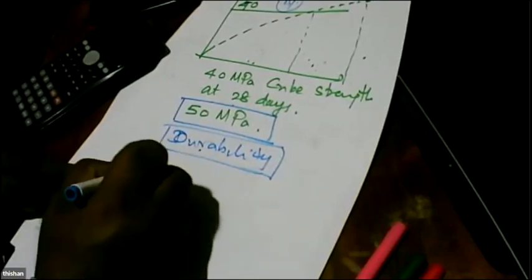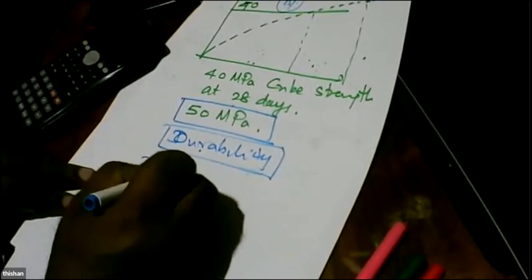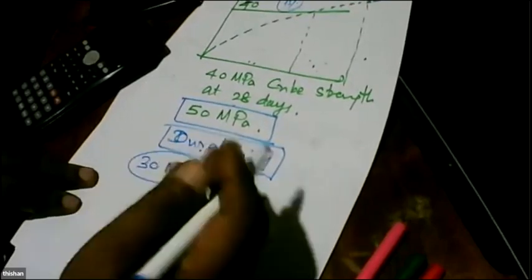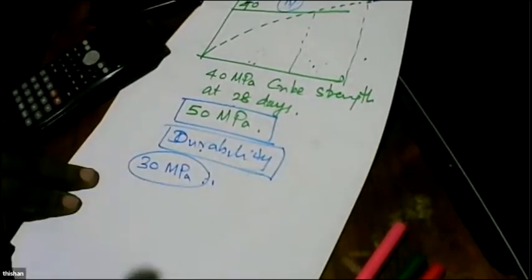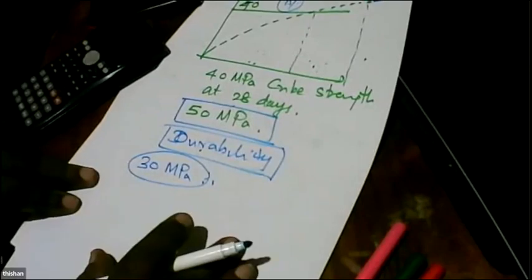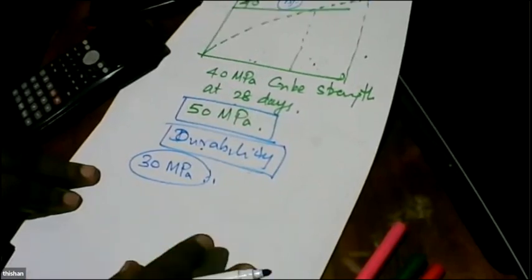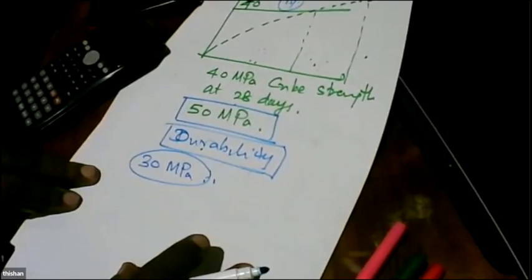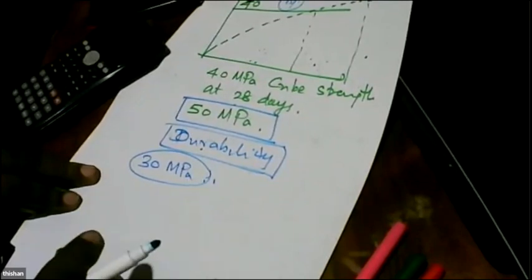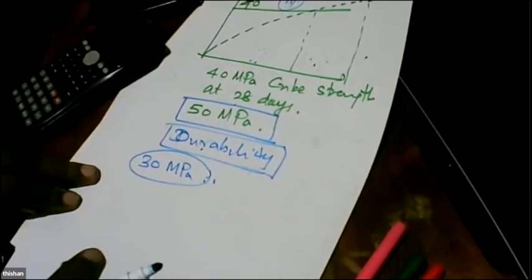If it is 30 megapascal or above, even 40 megapascal, 50 megapascal, you are going to end up with the same mass. So you can do the calculations and see. That is with my experience. I know if the bending moments are not very significant, like in our case, then the concrete strength is also not important as long as you have 30 megapascal minimum.